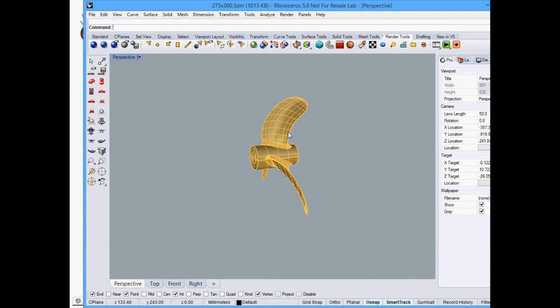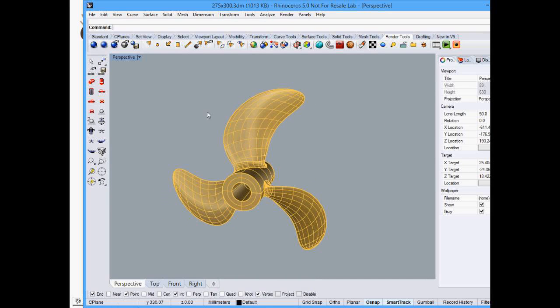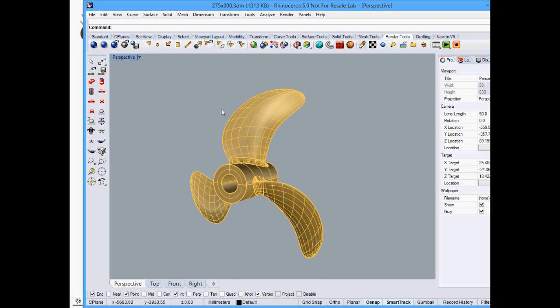We're going to treat this as if it was a real propeller, and we're going to basically pull points off the surface and enter them into Scan Converter. The first thing we need to do is pull some points off the surface. In order to do that, we need to choose an R over R position, intersect it with the surface, extract the curve, and pull some points specifically from that curve.